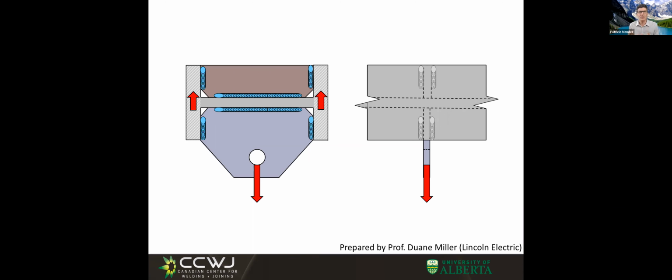The concept here so far is, let's weld on what is stiff and let's not weld on what is compliant, because what is compliant takes very little load, and the load would then be distributed into the stiffer parts. And you end up with a problem of stress concentration. That means you might end up breaking part of a weld.